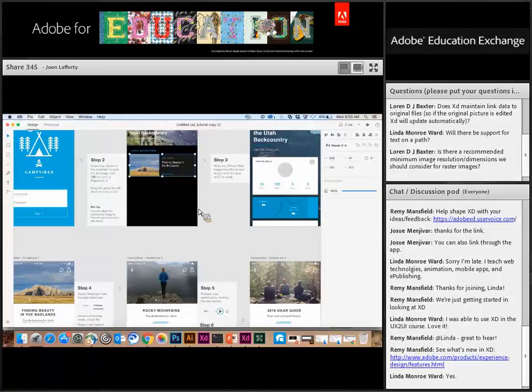then you export and you have the options. For design, it'll just get exported at 1x as a PNG. If you export for web, it'll be scaled at 1x and 2x. iOS is 1, 2, and 3x, and then for Android, it will export to all of these various resolutions and put it in the correct folder so it's ready for handoff to an Android developer.